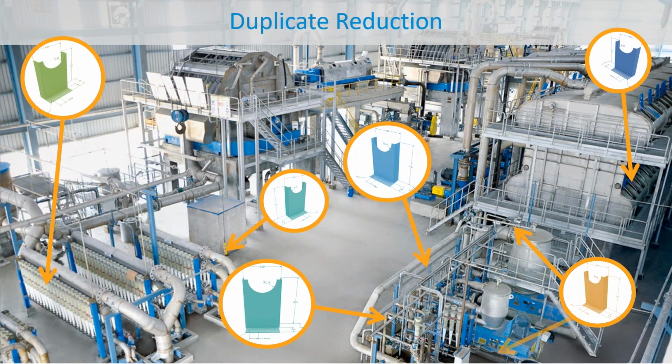because technically if they're duplicates, you should be able to replace them, as long as the geometry and some of the surface IDs, things like that, match up, and most of the time they match up pretty well. So if you're swapping them out in other assemblies with pretty much the exact same file, there's really not a lot of extra work that you have to do in Inventor. You can actually do that in bulk from Vault using the replace function there. So it's something to think about, getting rid of some of the clutter in your Vault. More and more customers too, Vaults are getting larger all the time.